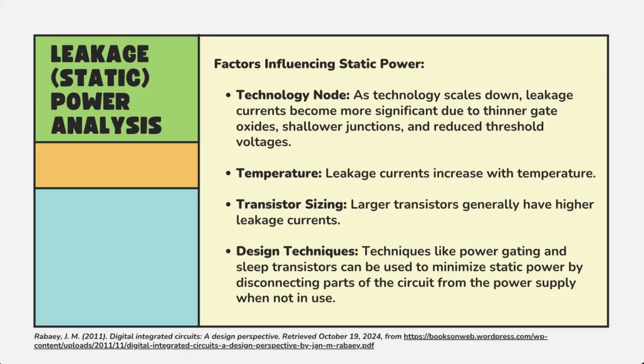Transistor sizing. Larger transistors generally have higher leakage current. Design techniques. Techniques like power gating and sleep transistors can be used to minimize static power by disconnecting parts of the circuit from the power supply when not in use.